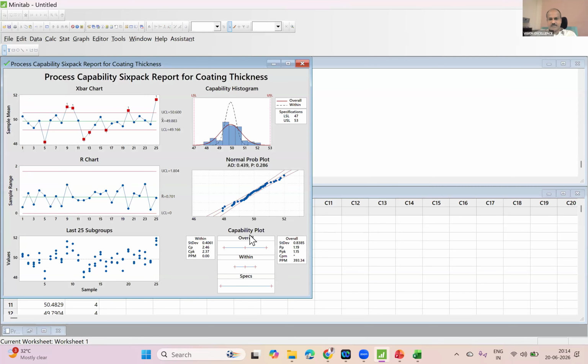This is the capability analysis report. And first you look at CP/CPK. Look at your CP. How much is it? 2.46. CPK 2.37. That means excellent for short term. Now you should know what is short term. Short term means you just want to produce a small batch size. Let's say you want to produce 300 or 3,000 pieces, and it's a small order. Now CP/CPK is good. Now you can run the process and then complete the entire order processing. There is no problem at all.